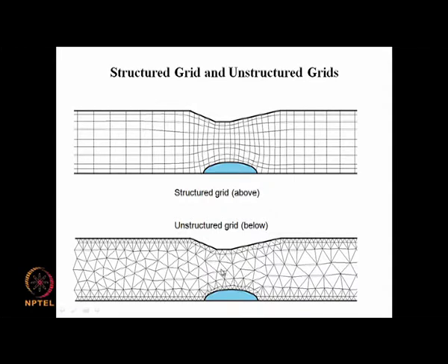So, in that sense the number of neighbors is not fixed in this unstructured grid. But whether you do the discretization on the structured grid or on the unstructured grid, we still end up with an equation like A phi equal to B, which we have seen. Okay. And in the case of structured grid in 2D here, for the diffusion equation, for the Laplace or Poisson equation, we will have the 4 immediate neighbors. That is, for point ij we have i+1,j, i,j+1, i,j-1 and i-1,j.